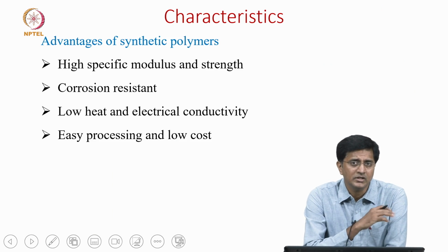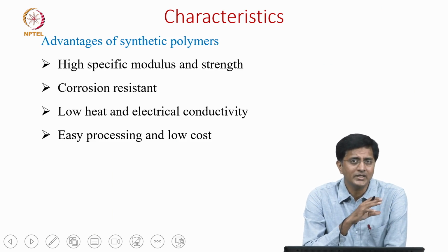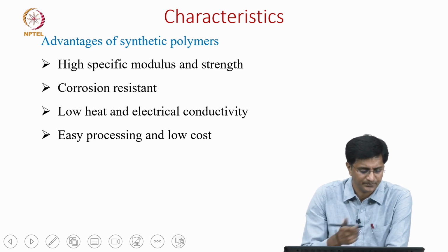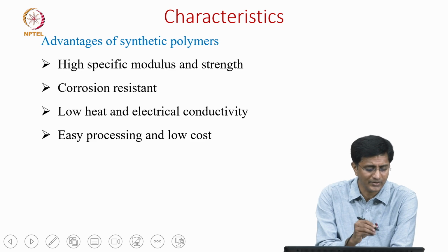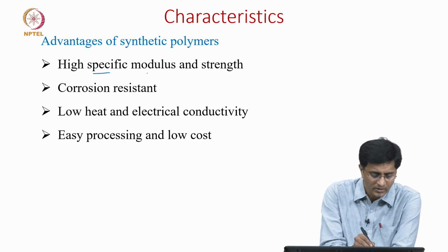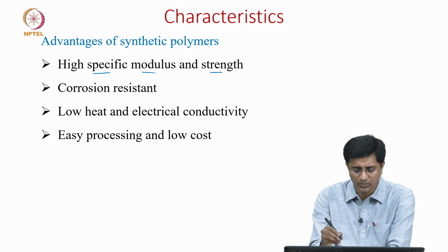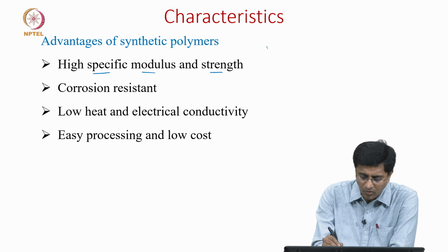So, having seen a few polymers, now let us look at the characteristics of these polymers and see why they are very popular and used in our daily lives as well as in our specific specialized applications. So, we will start with the advantages of these synthetic polymers. To start with, high specific modulus and strength. So, what is specific modulus? Specific modulus is nothing but modulus by density.